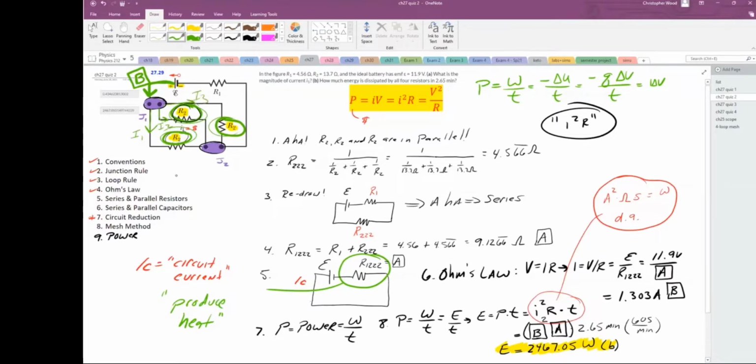And I'm just saying in the name of expediency, and it's good to see the simplifications, because these three resistors all have the same value, they're going to draw current at the same rate. So I'm going to say I1 equals I2 equals I3. They're all the same currents. So let's take that circuit current, whatever is living there in calculator memory location B, which I figured out right here. Let's divide that by 3.